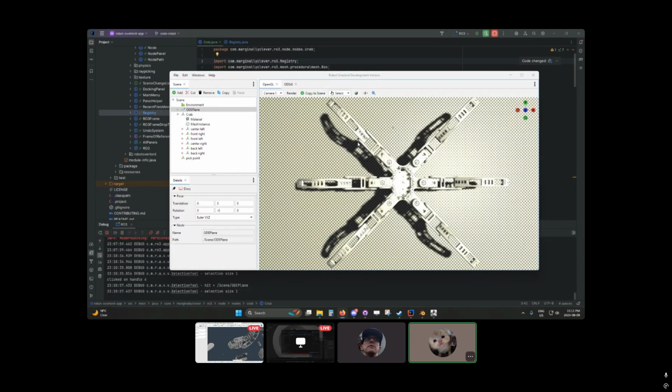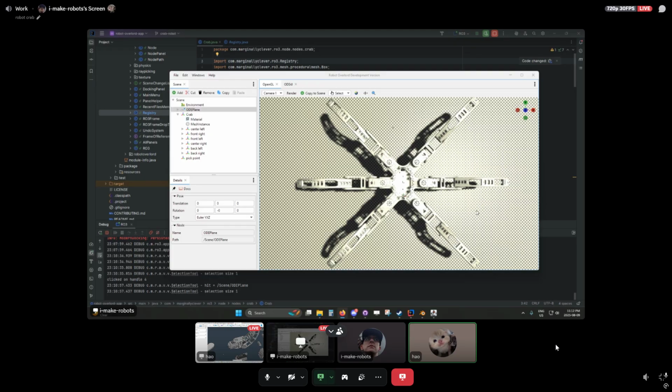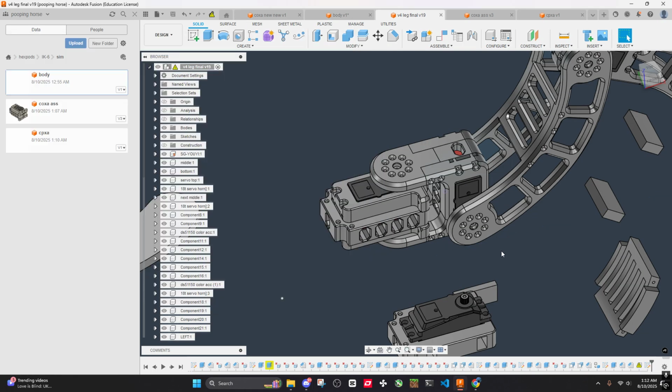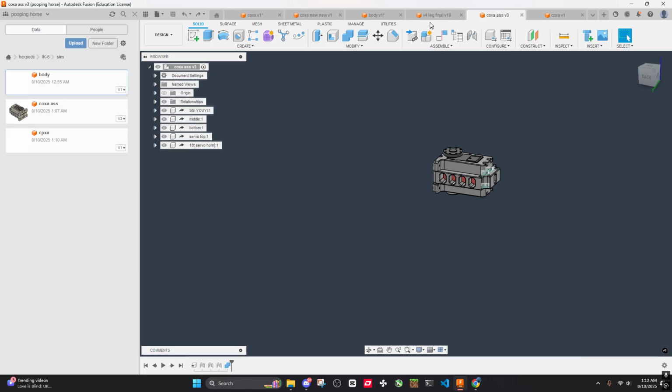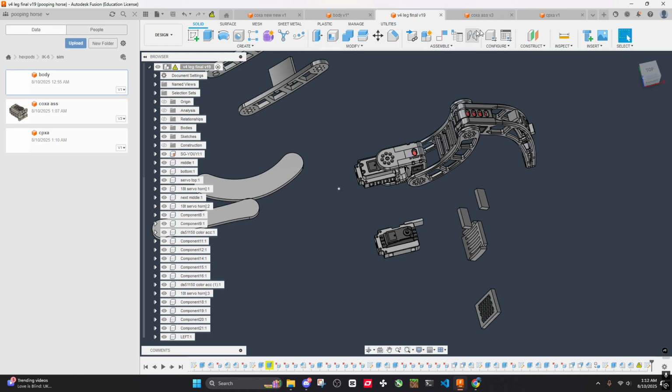So we can just offset the coxa joint, the front 2 legs and the back 2 legs, by a few degrees. For the initial position, the way it's mechanically constructed, it would look like this, and then maybe at runtime we tell them to rotate a few more degrees, one way or the other. Yeah, sure. And that could improve the feet not hitting each other. It could. This is testable. We don't have to debate it. We can just build an example and test it. Yes. Okay. But I like where you're going with that. We can definitely revisit that idea.